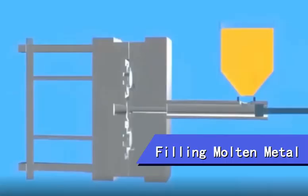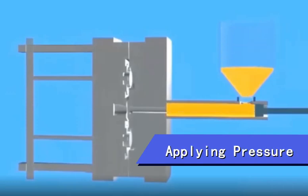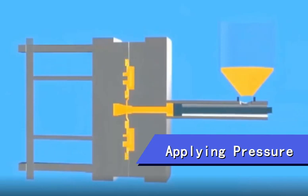Filling molten metal. A barrel is filled with molten metal, which is then pushed into the die cavities with a piston. The piston applies pressure to the metal as it fills the die. Applying pressure. Once the molten metal has filled the die cavity, pressure is applied to the metal to ensure that it fills all the intricate details of the die cavity and solidifies quickly.